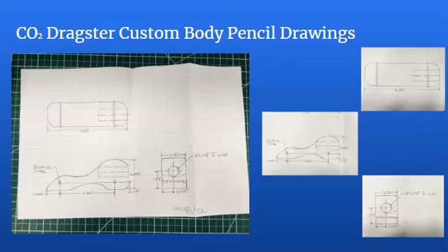I estimated my size dimensions based off the wooden block given to us in the beginning of the project. I will later use this block of wood to cut out my custom body. Something that I want to point out is the shape of my car. The roundness shape is great when it comes to laminar airflow, because there aren't any rough edges or stops, the air will just have to move alongside the body. This will greatly reduce drag.